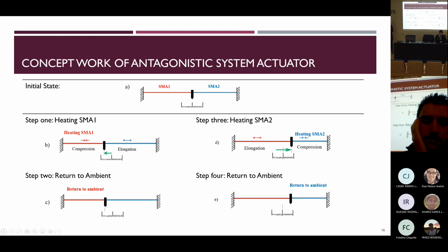However, shape memory alloy is not that easy to apply voltage to and measure displacement, since it has a crystalline structure. So each time we need to apply voltage on one wire and heat it. Voltage leads to temperature, so we are heating the wire. We need to cool it again in order to preserve its main crystalline structure.